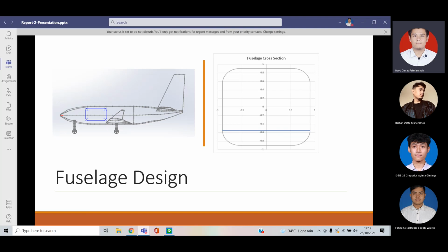We decided that the door would be 2 meters by 1.2 meters because it is big enough to accommodate larger loads without affecting the structural integrity. There is also a fillet to add structural strength. It is positioned on the left side in front of the wing because it is the largest surface area where we can put the cargo door.